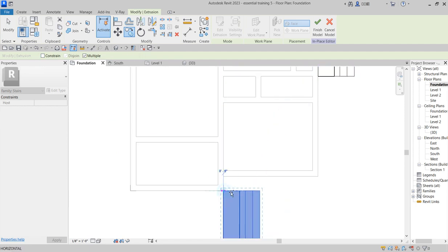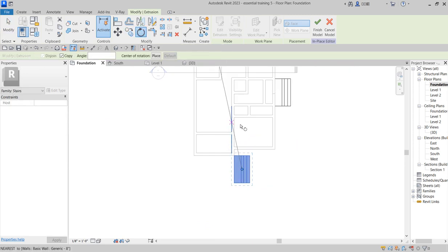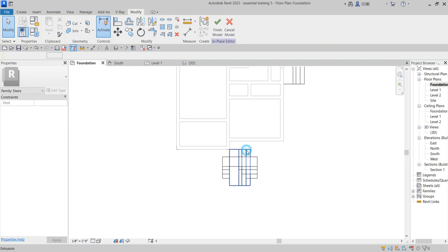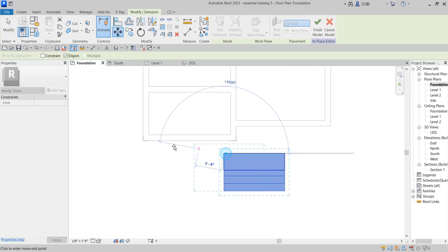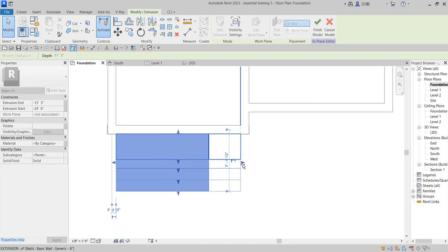You drop it at one angle, snap to that level, then you pick it here and say it should rotate. So you rotate at 90 degrees perfectly. Now you delete the former one, the vertical one, and adjust this one to snap to the wall, then you stretch it the same way.